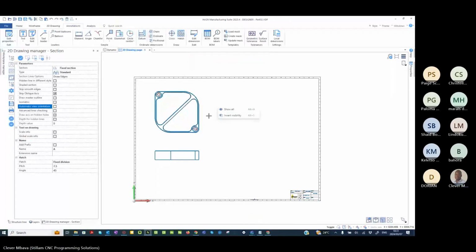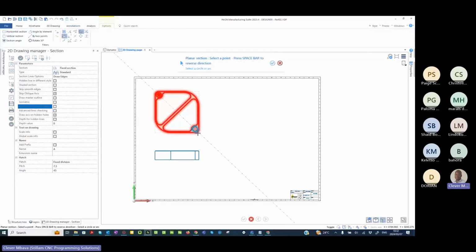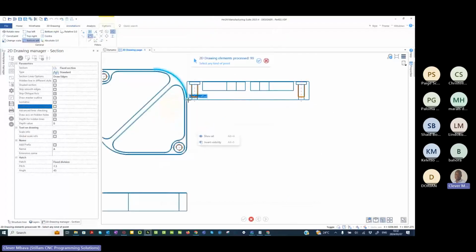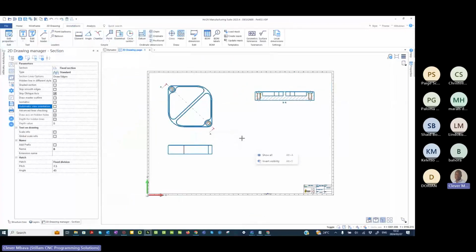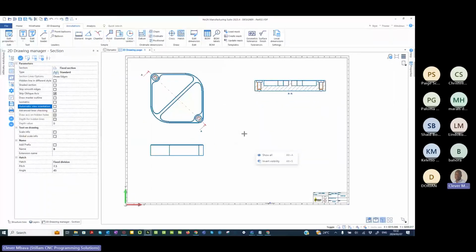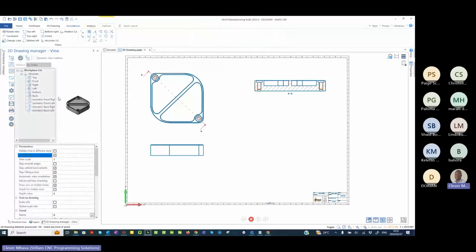It is this one by 2, and I go this one, and that's left click, and then I can right click. Going to position it where I would like it to go and sit, so I can position it right there. We can see the way it's sitting, right? And it is possible for me to bring some other sides as well, detailed sides. I can say I want the isometric part of it from here. So if I go and say I need the shaded view of that as an isometric, I can bring it and position it. You can see there.